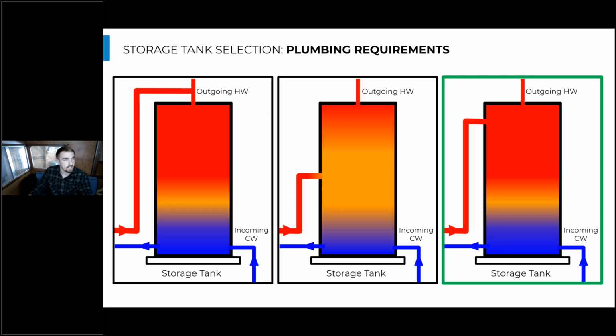And then the last connection that I've seen in the field is connecting the heat pump line straight to the hot water outlet, right? In theory, you would think this would work really well because our heat pumps are actually producing a specific water temperature independent of the entering water. But in practice, anytime the heat pump turns off, there is a segment in time that this line will just cool down.